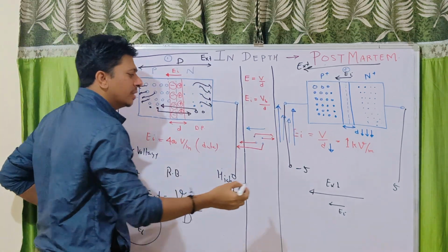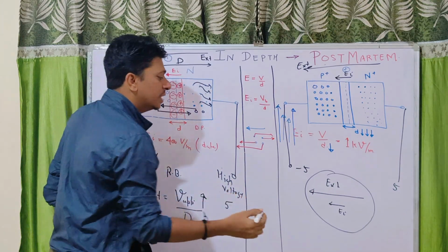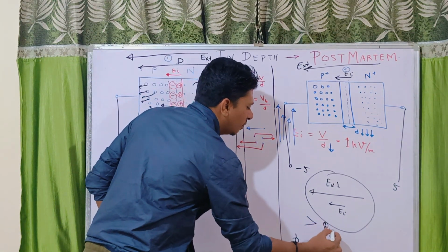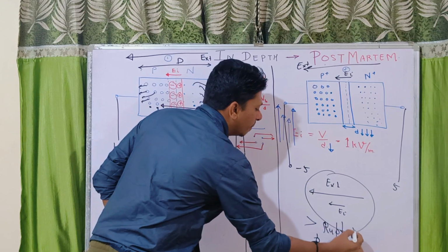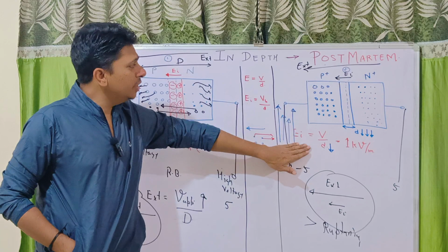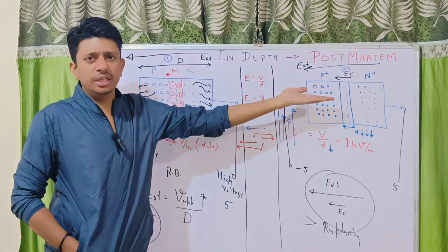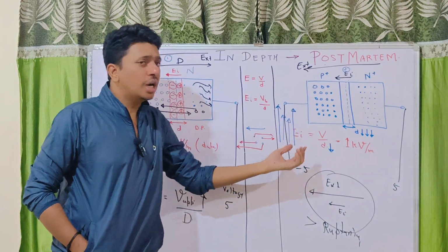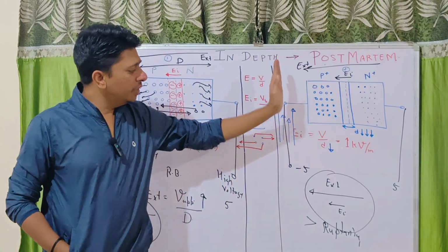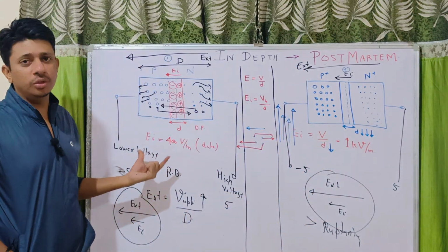But in this case, together at a very small voltage, they are capable enough to cause sudden rupturing of covalent bonds. And why is this capable enough? Because already, due to this concentration variation or enhancement in the concentration, we have achieved a high electric field initially, and this is very useful for voltage regulator circuits as compared to this one.